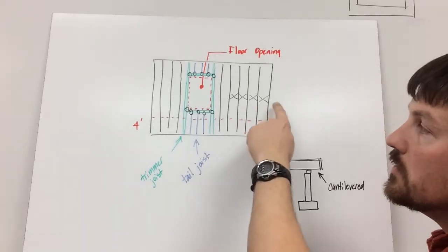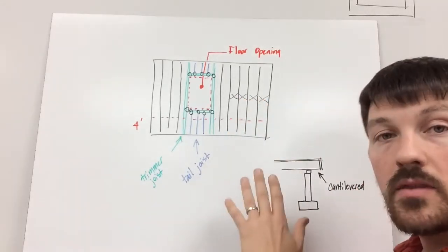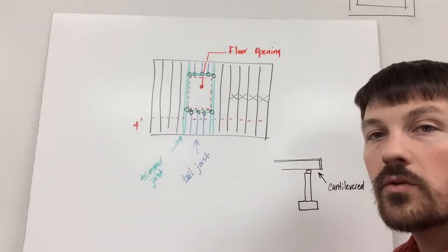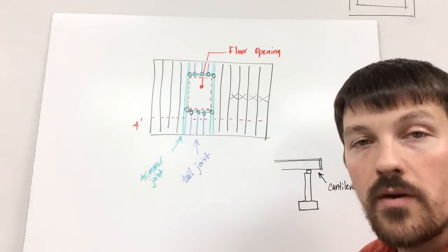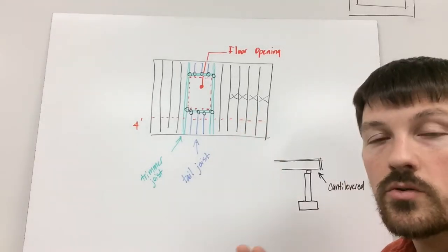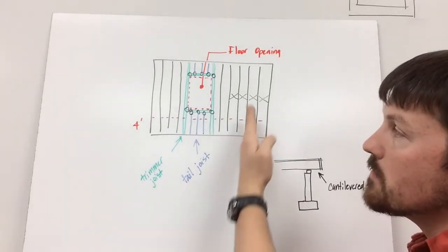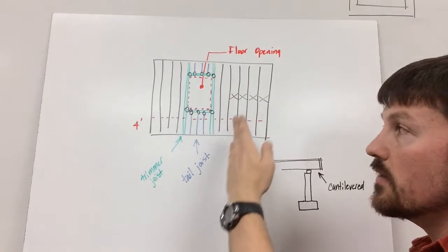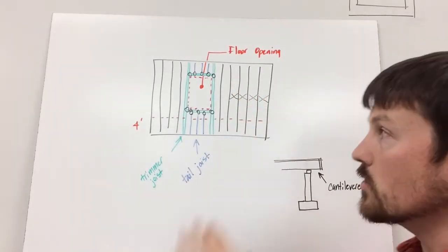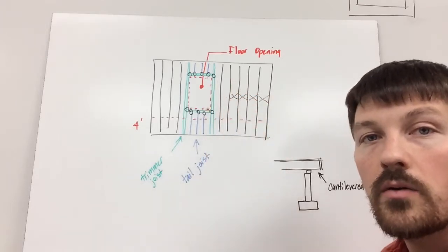And lastly, when you put on your cross bridging, you're going to nail the tops and leave the bottoms until after we have put the subfloor down. Once the subfloor is down, you nail them from below. That way, if you have to move or adjust these floor joists as you're putting down subfloor to keep them on layout, because they may not have stayed straight, and they're a little bit off, if you had nailed them down, they wouldn't move. So you want to leave them loose, put down your subfloor, and then nail from below and lock them in place.